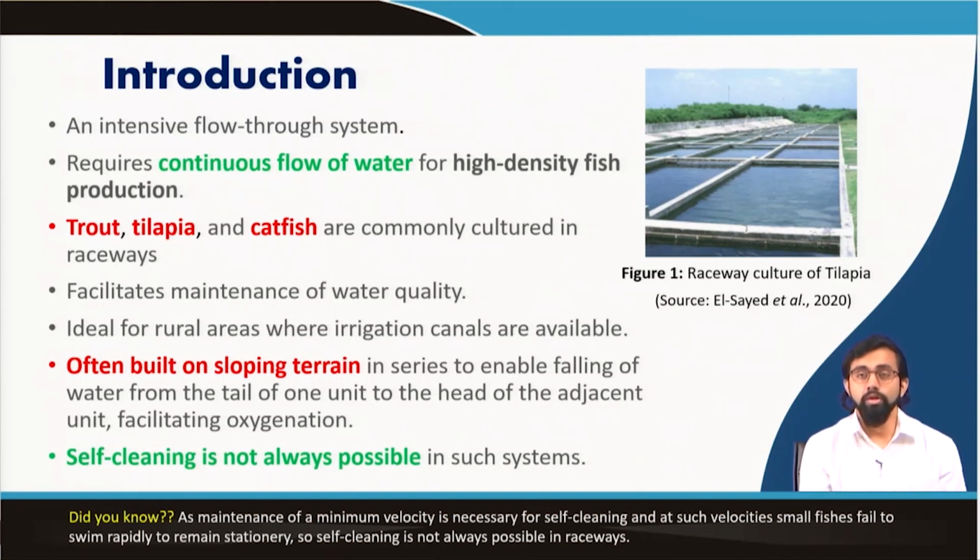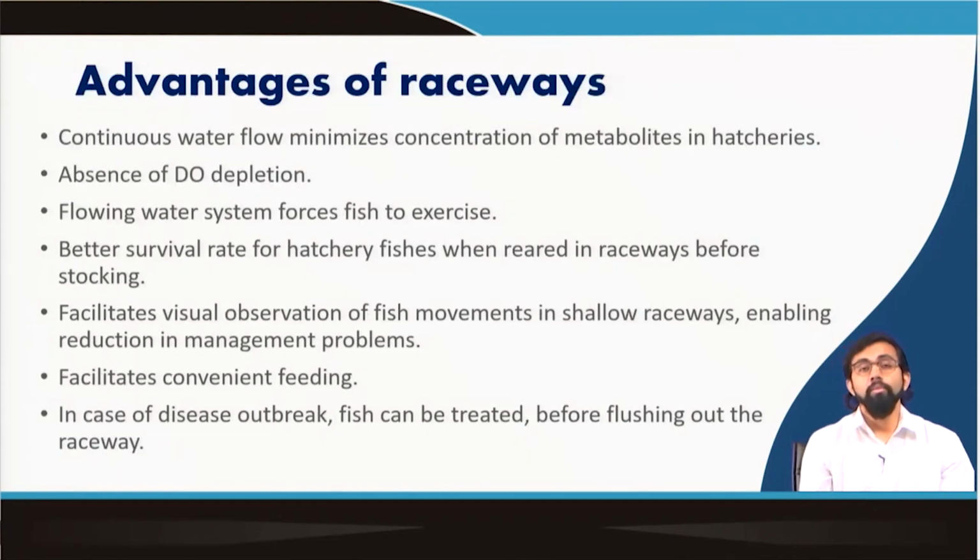So that's why the water flow should be as low as possible, but not so low that the water is not in a continuous flow condition. Continuity has to be maintained, but the self cleaning velocity cannot be approached in this kind of system. That's one of the major drawbacks. Scientists and people all over the world are working on it, and there are a lot of technologies already available, and there are technologies which will definitely be available in the near future.